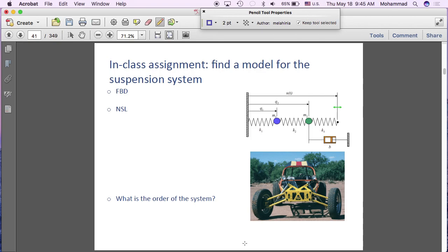We also have an energy dissipation element, either intentionally, like a dashpot, like a damper, or the fact that any mechanical element is not an ideal energy storage and energy release. And every time you put energy into a tire, it doesn't release it all back. So we have some dissipation. So we have to capture that loss of energy somehow. And what we are doing is we are capturing it as a damper, as a viscous damper.